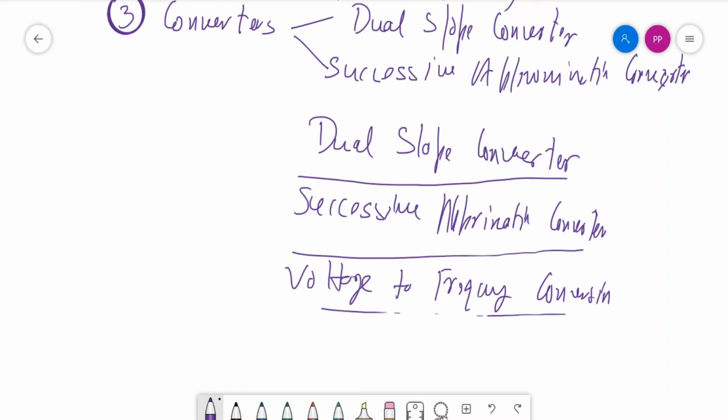So accordingly circuit connection has to be made, and the output of the integrator goes to a comparator which compares it with a negative reference voltage, and as soon as the output of the integrator goes below this negative reference voltage while charging the plates, it will generate a negative pulse which will trigger the pulse generator, and this pulse generator will trigger a train of pulses, possibly the grounding pulse, which will discharge the capacitor fast, and this process of charging and discharging will repeat to keep a frequency at the output of the comparator which is basically proportional to the input voltage to the integrator.